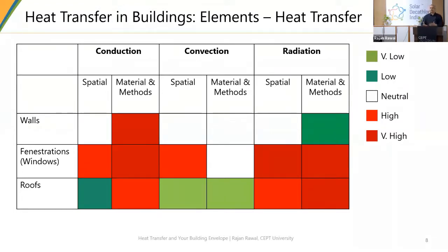One of my professors, Dr. Bansal, used to use one phrase very often: all buildings are low pass filters. That means whatever happens outside in a naturally ventilated environment will happen inside eventually, but how long it takes depends upon your envelope characteristics. So thermal mass will become a liability if you are not managing it very well.